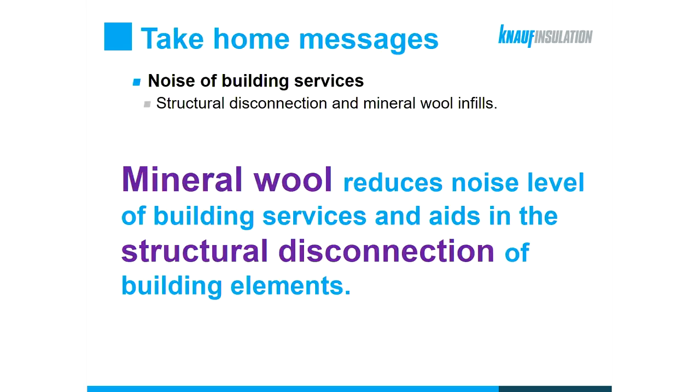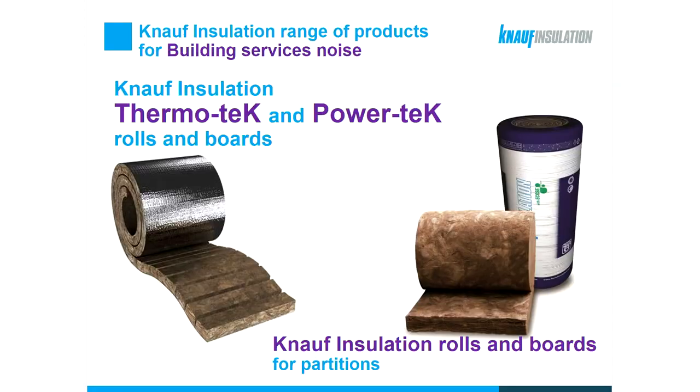So to summarize this part of the noise of building services, we have highlighted the importance of a structural disconnection and mineral wool infills. But again, owing to its porous structure, mineral wool is highly effective in reducing noise levels of building services, as well as aids in the structural disconnection of building elements.